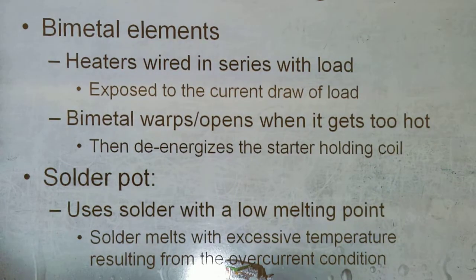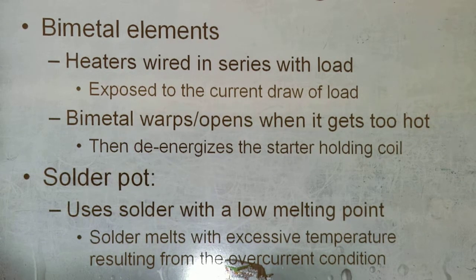Temperature sensing devices, bimetal elements, heaters wired in series with load, exposed to the current draw of load. Bimetal warps or opens when it gets too hot, then de-energizes the starter holding coil.